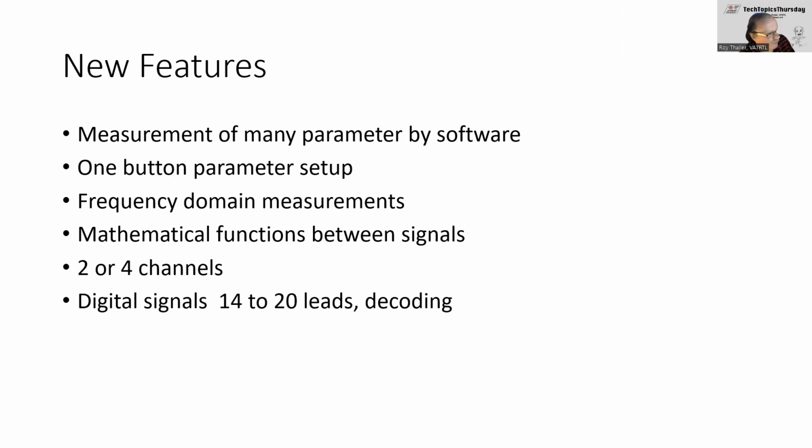If you want to build HF transmitters, going up to 30 megahertz, which means probably going up to about 100 megahertz, 150 megahertz would probably be okay if you want to look at the signal. If you really want to get into UHF and VHF, that's where you need a gigahertz, 1 gigahertz or more oscilloscope. And you're going to pay the price for it. A lot of people aren't experimenting with VHF or UHF because the test instruments are quite expensive. There are other ways of doing it to see if it works or not. So it depends what your goal is in getting an oscilloscope. You have to put some thought into it.